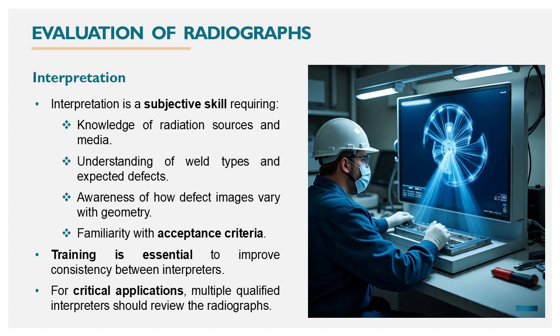Interpretation. Interpretation is a subjective skill requiring knowledge of radiation sources and media, understanding of weld types and expected defects, awareness of how defect images vary with geometry, and familiarity with acceptance criteria. Training is essential to improve consistency between interpreters. For critical applications, multiple qualified interpreters should review the radiographs.